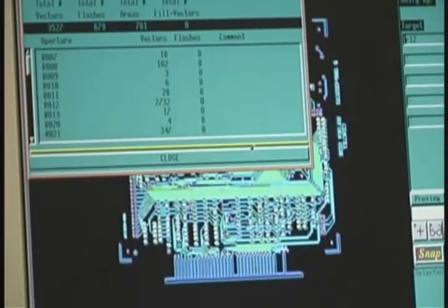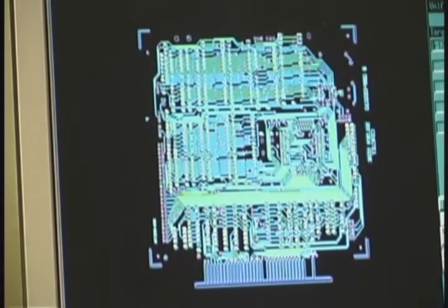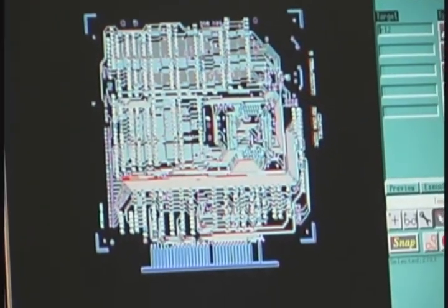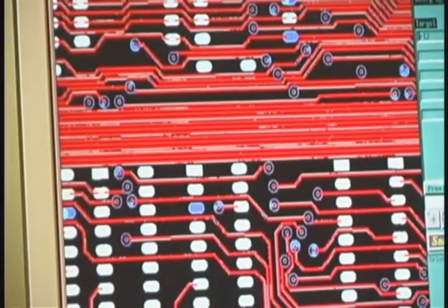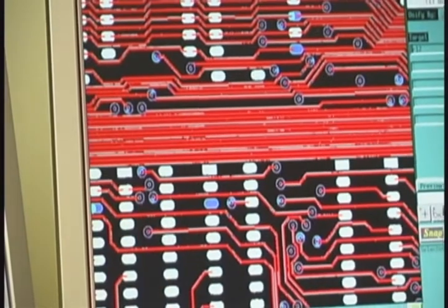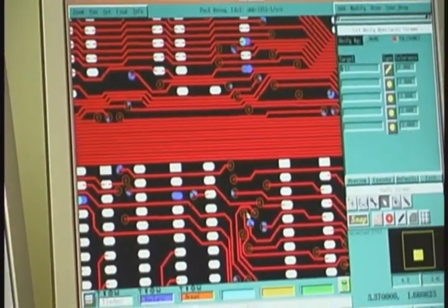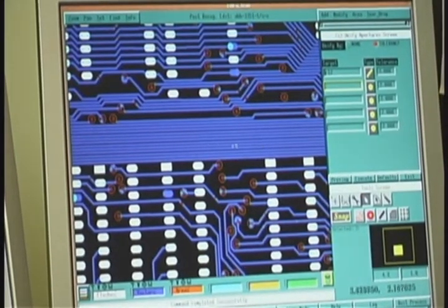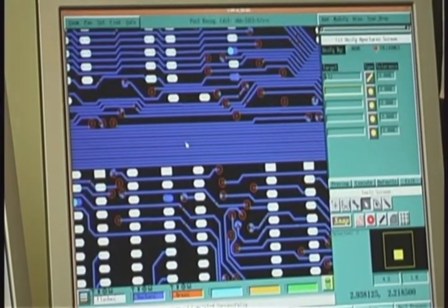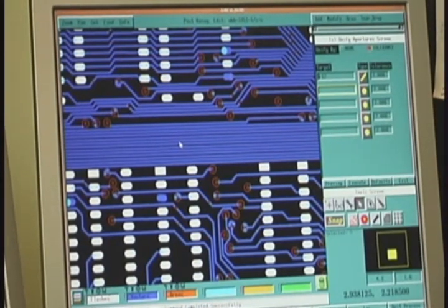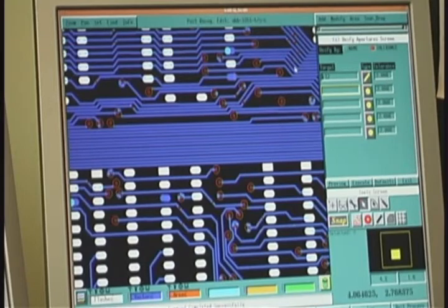When you do that, you preview the layers, you're going to see that everything that is around 12 with a plus or minus 2 mils is going to highlight, and that's why all the vectors turn red. And when you execute that, if you query any of these traces, it's going to be a round 12 aperture. After we do that, then we move to editing.